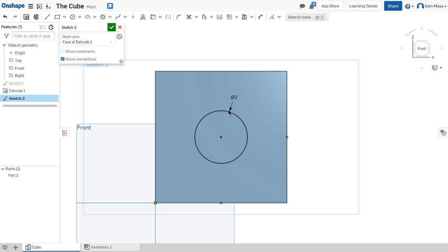Also, I'm going to show you a line real quick. So I did this, right? I'm going to hit escape. This cannot be extruded because it's not a polygon, because it's not closed. But if I did a line from here to here, notice how it turns gray.